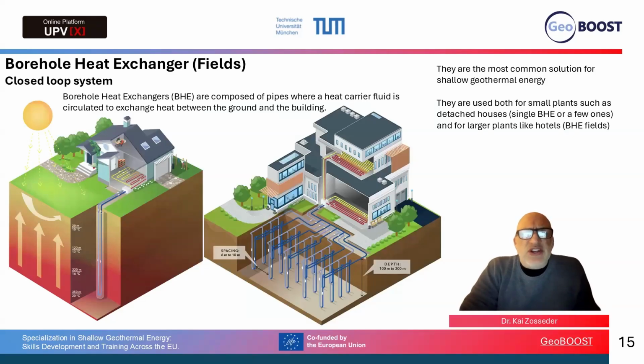Borehole heat exchangers are one of the most common solutions for shallow geothermal energy. So, the most installed system. It's a closed loop system, and how it looks, you see here on the left side: we have pipes which carry a heat carrier fluid, which is circulated in the underground in some pipes and collects the heat to a specific depth, and then leads the heat to the heat exchanger system and to the heat pump, and then this circulation starts again.